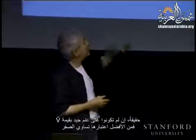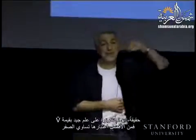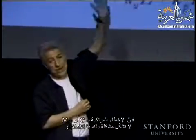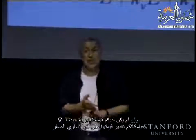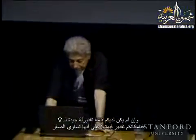So in fact, if you do not know V hat well, it's better just to treat V hat as equal to 0 rather than making a wrong estimate. So besides V hat, errors in G or in M are not a problem for the stability, it's V hat. And if you don't have a good estimate, you can just use a 0 estimate of V hat. Okay.